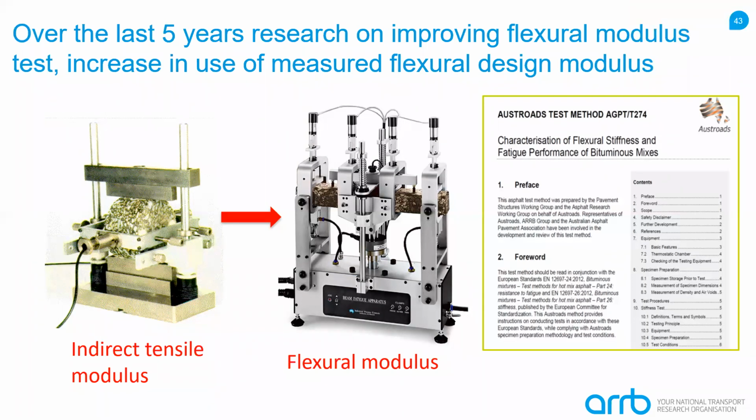Thank you, Jeff. And next question is, fatigue life of a subgrade material, which is black soil, stabilized with cement and additives, to be examined. And they believe that this material behaves as a bound material. And what test method would you recommend for this evaluation, whether stabilized material approach or asphalt material testing approach?